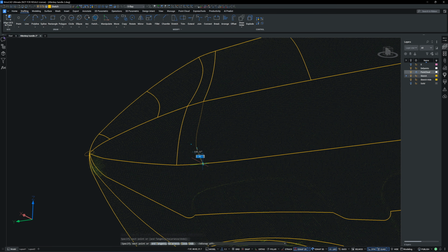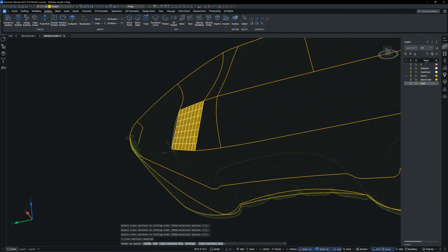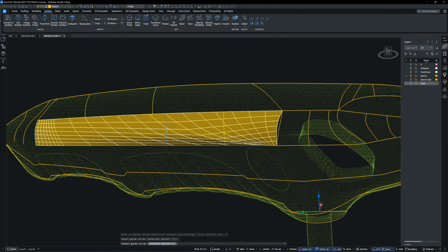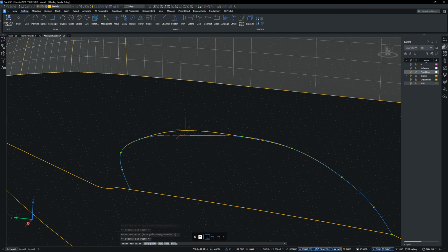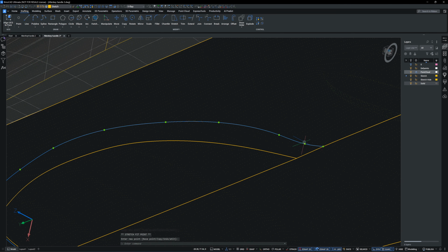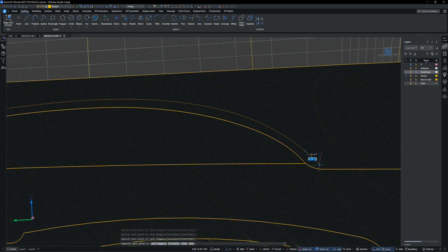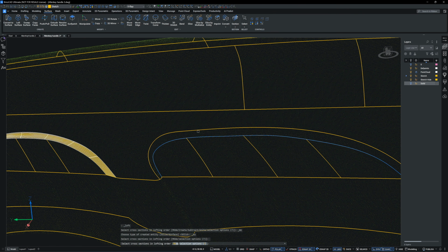You might wonder why anyone would want to reverse engineer an organic shape like this into a CAD model. The reason is that models like this are often created by artists or product designers in polygon modeling software such as 3ds Max, Maya, or Blender, and it needs to be converted into a CAD model to generate a STEP file for CNC machining.